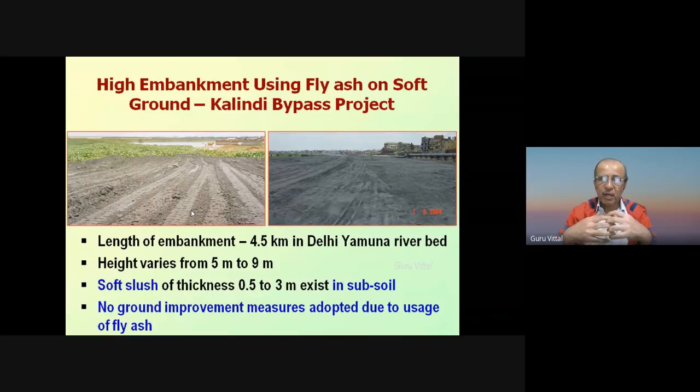So that's why we have to adopt what we call a ground improvement technique. We have to improve our subsoil. What do they do usually in such a case is that they adopt what they call stone columns. So what are these stone columns? We make a borehole, take out that slush, backfill that borehole with graded stone aggregates, compact it, and so it becomes a stone column. Several stone columns are laid out, and it becomes a composite ground, and so its bearing capacity also increases. In this manner, we eliminate or reduce the settlement that is going to take place.